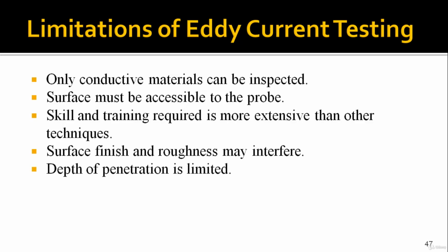Depth of penetration is limited. In ultrasonic testing you can find defects throughout the material, but here you can only find surface and near surface defects, up to about 37% of the thickness depth. Otherwise it is not possible to find defects throughout the material.